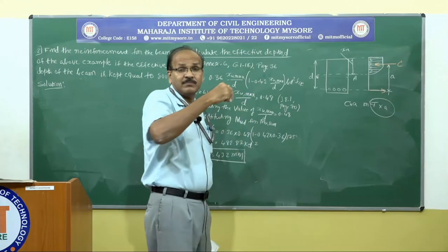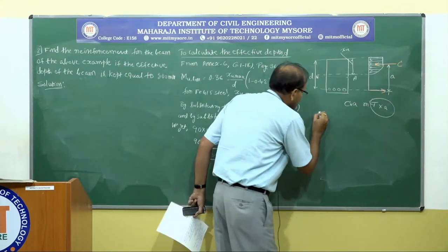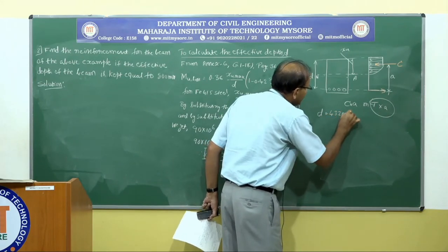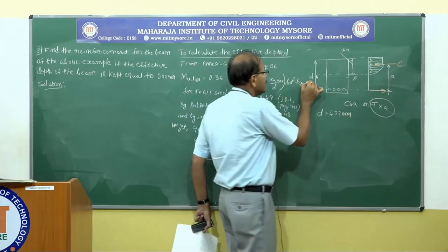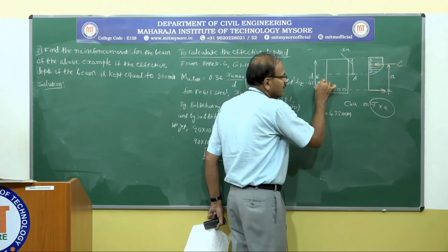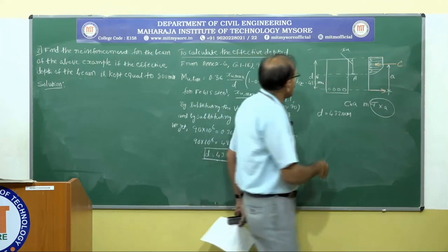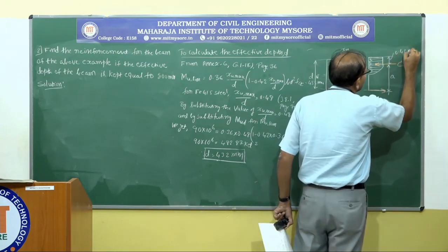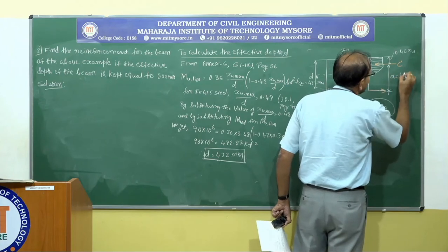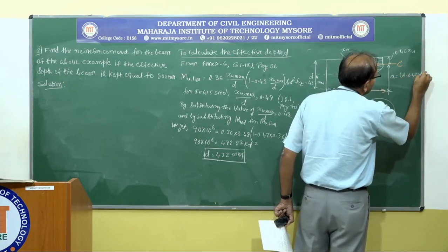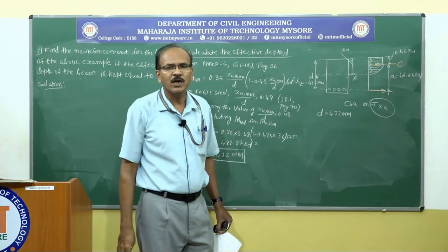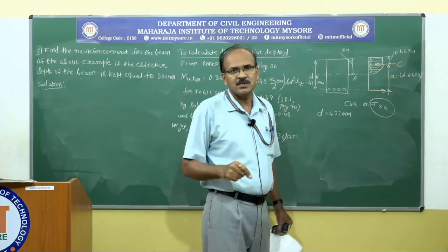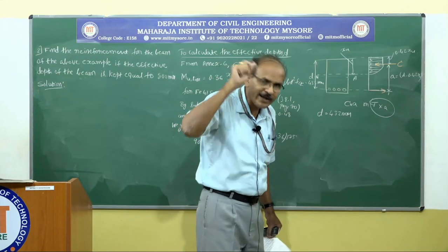So, in the previous example, if you remember, for a balanced section, the effective depth required is 432 millimeter. And when this is d, this is going to be 0.42 xu. So, lever arm is d minus 0.42 xu. Is it not? So, to take care of the moment of 60 kilonewton meter service moment, and the ultimate moment is 90 kilonewton meter.